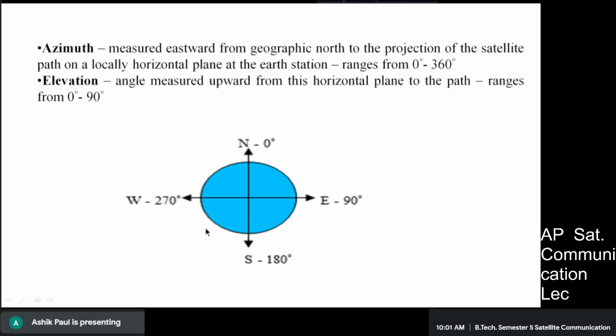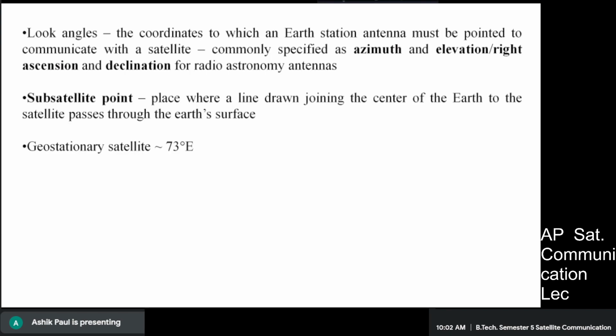If we are trying to track the signal from Kolkata, Kolkata is somewhere at the center of this figure. So it will be either southeast or southwest. Now, as somebody has already mentioned, the longitude of Kolkata is 88.5 degrees east, while the subsatellite point of this particular satellite is 73 degrees east.